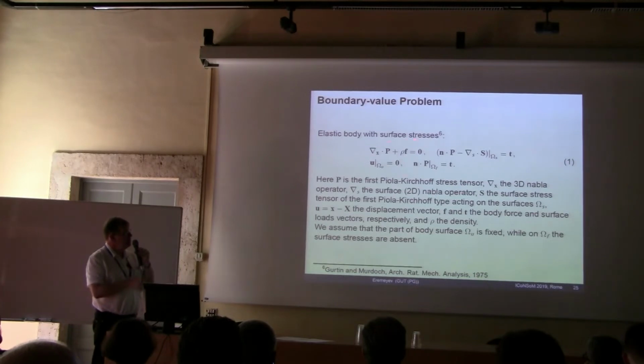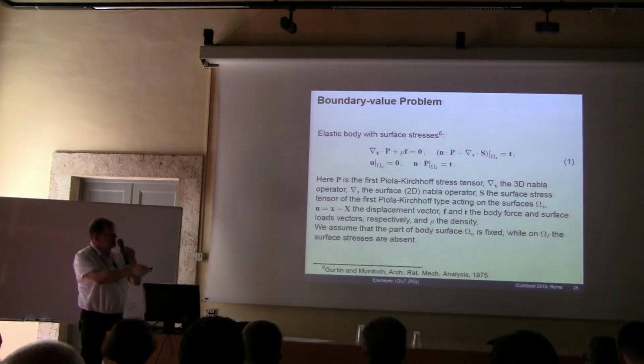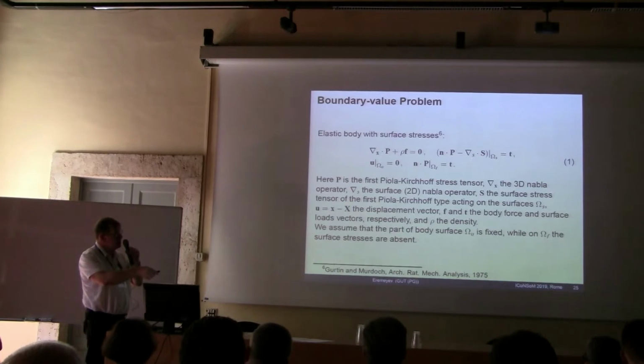We have the typical Lagrangian equation, the equilibrium equation in the bulk with classical boundary conditions. And what we have additionally are traction conditions where we have the surface stress tensor, and this is just a generalization of the famous Laplace equation to the case of surface elasticity.